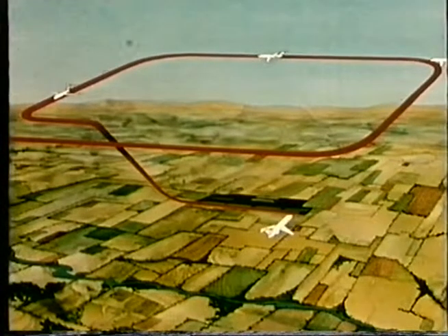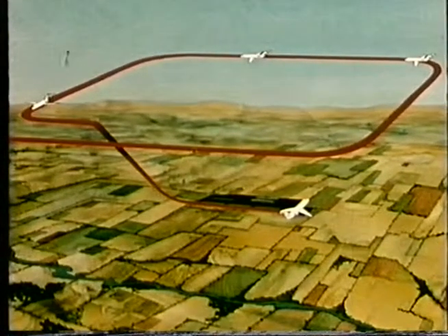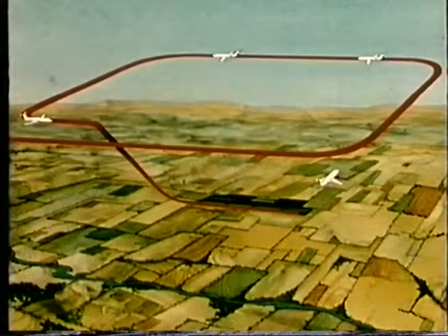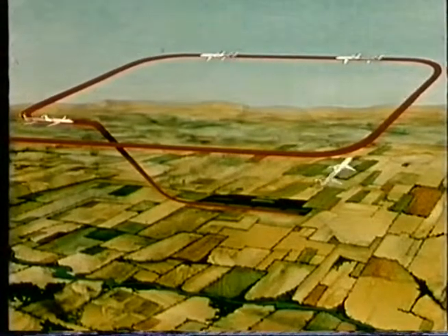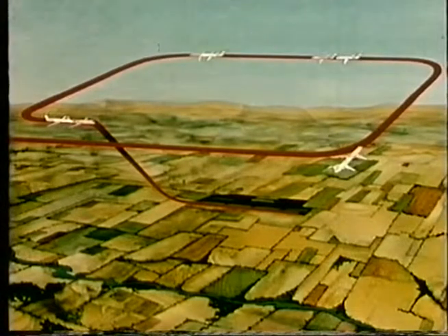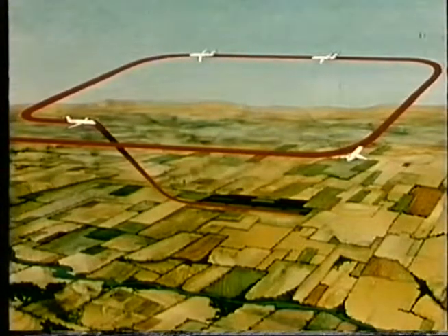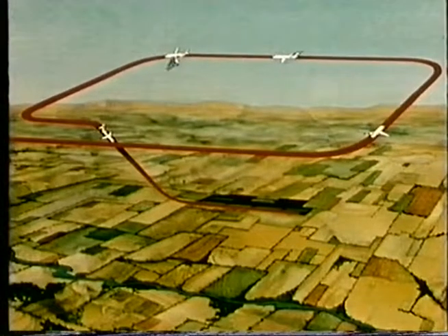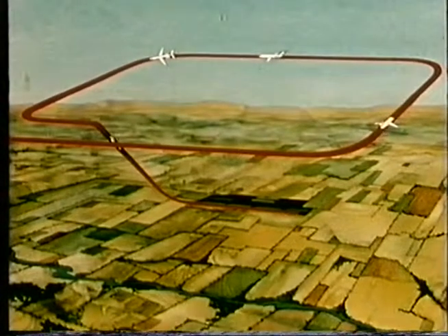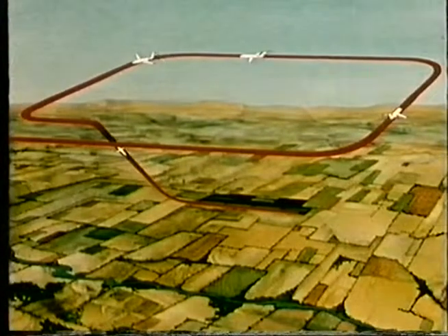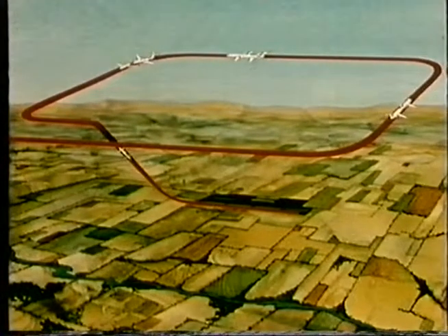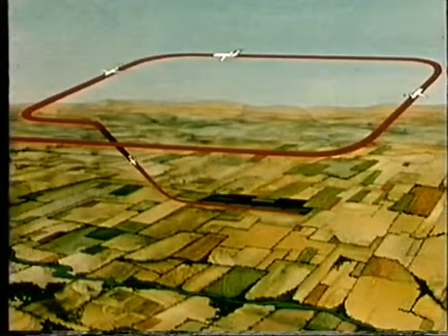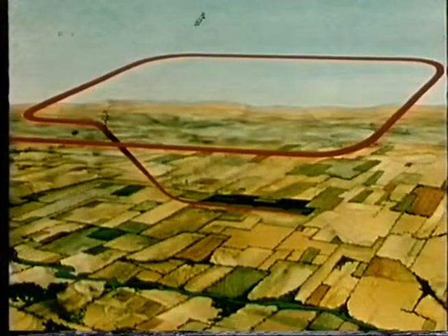He informs the pilot in command of his number in the landing sequence by a clearance, such as "continue approach, number 3 to land, follow the DC-8 turning onto base leg." The pilot in command positions the aircraft in accordance with the instructions contained in the clearance and adjusts his speed or his circuit to ensure the proper spacing.